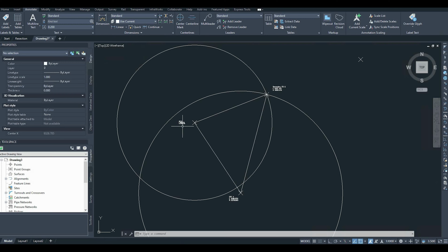And then you can add the dimensions here for each line, and also you can measure this angle X and compare it against the measured value of X as well. For example, to measure a value, you would go to annotate, go to dimensions here, guys, annotate again on the top bar. I would go here to dimensions, open this list. Here you will have angular measurement. I would pick this angular measurement, guys, and then I would say I would like to measure the angle between this line, pick it, and this line. Okay, and then this is my angle, one click.